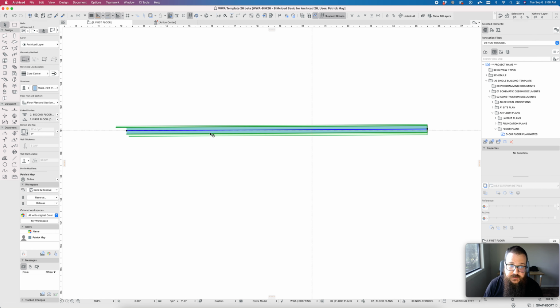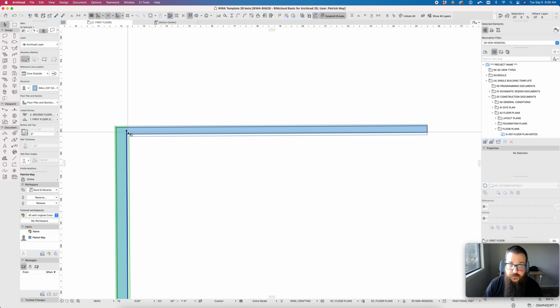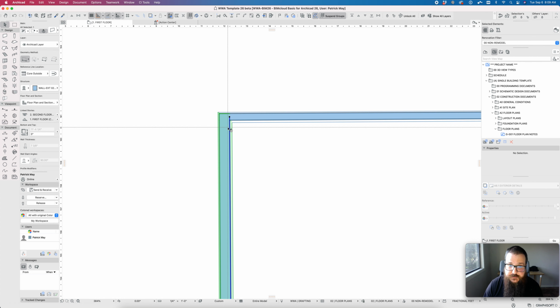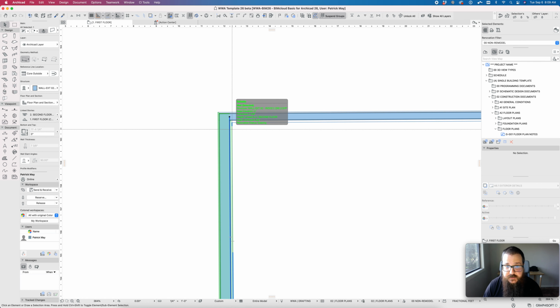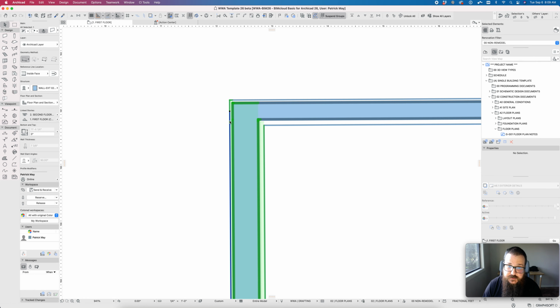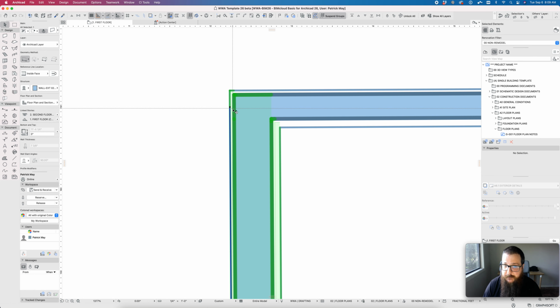If it's a steel building, it probably makes sense to put that on the center of the wall. If it's a light wood frame building, it might make sense for that reference line to be on the face of stud. But place the wall deliberately so that as the wall may grow or shrink, or siding and finishes may grow or shrink in the future, that constant is in a fixed position. For most projects, the inside or outside face of finish is going to be one of the worst positions to put that.